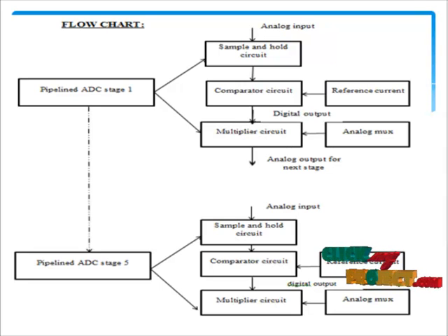Multi-bit stages can be used, however a high bit number is limited by offset in the comparators, so we use the comparators of flash ADCs. In this design we use a 4-bit flash stage, a 3-bit stage and a 2.5-bit stage.